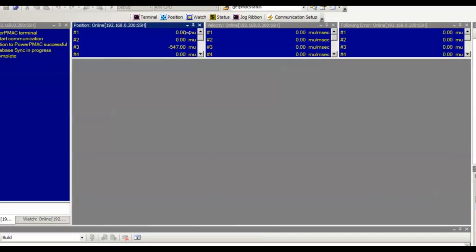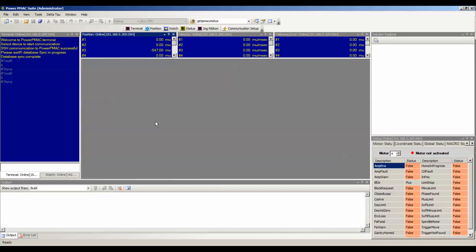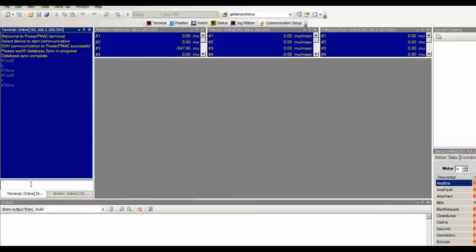You can see here in the position window that the position for motor 1 has been reset to 0. This makes observing changes in position much easier because you can compare them relative to 0 rather than some arbitrary position. Now I want to issue an Out0 command and observe in which direction the motor moves, whether positive or negative. For motor 1, this command is #1 Out0.